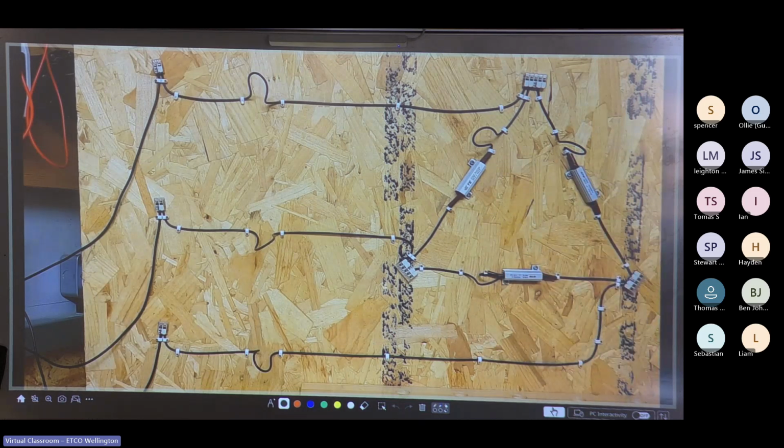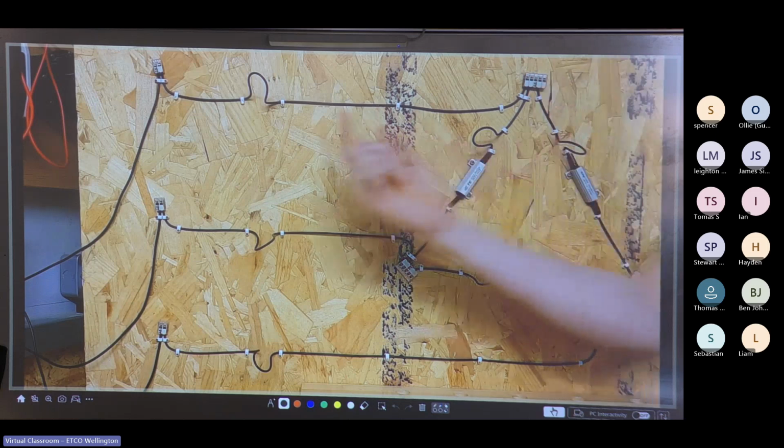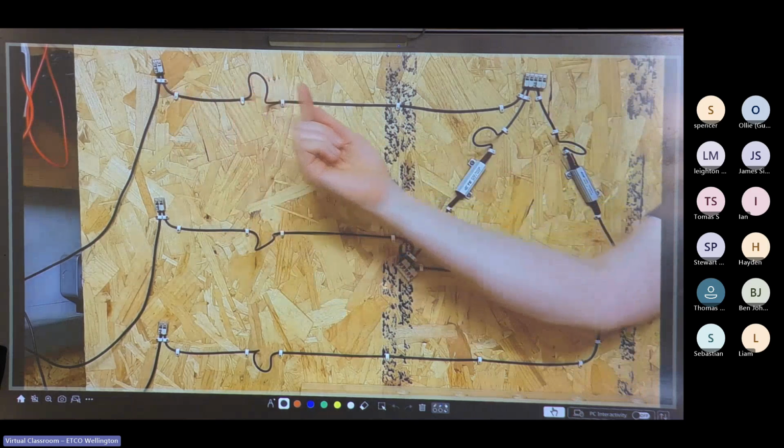And understanding that is going to help us to understand the relationship between line voltage and phase voltage in this delta connected system. Moving on now, we've got our line current and our phase current. So remember, the line current is still the same definition as it was before. It's the current that flows through the supply line.